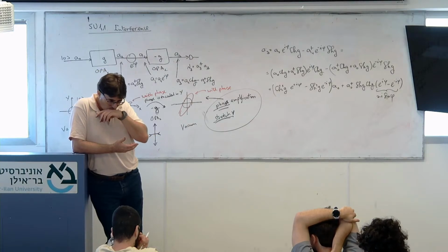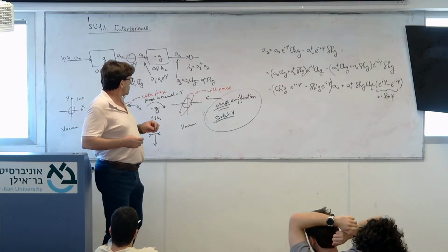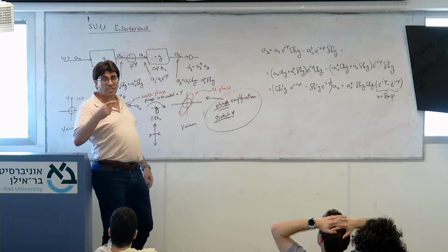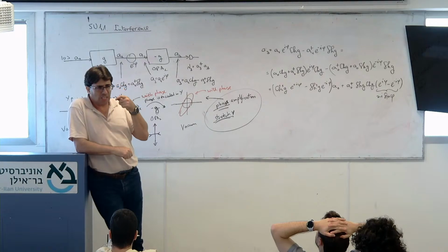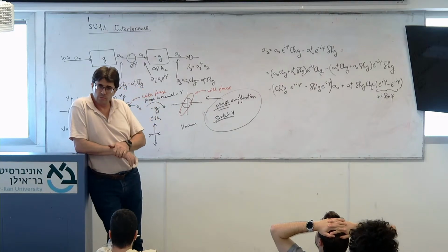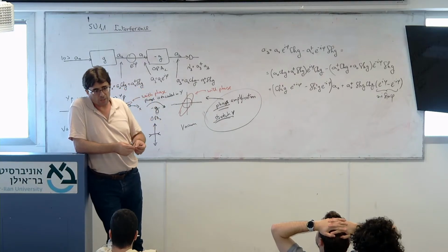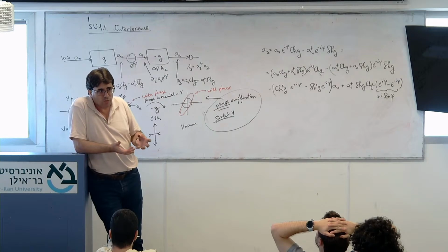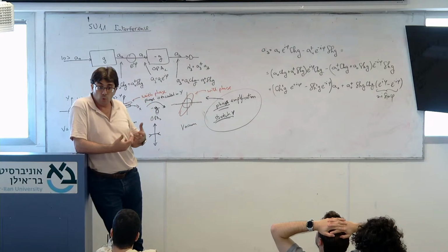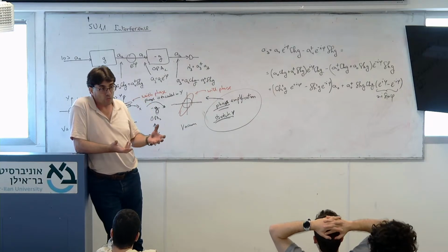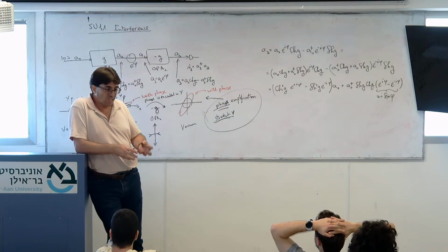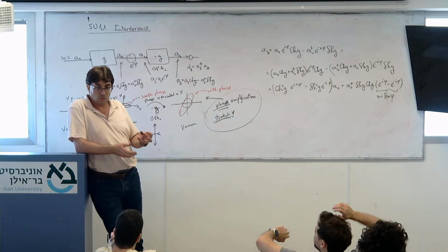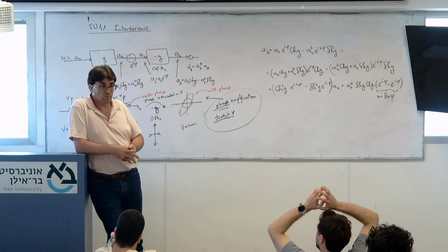So now, what did we have before? We had quantum noise, and now we reduced the noise. Good, great, but can my detector measure that reduced noise? Could it even measure the noise before? Most detectors are not shot noise limited, because their internal noise is larger than the optical noise.